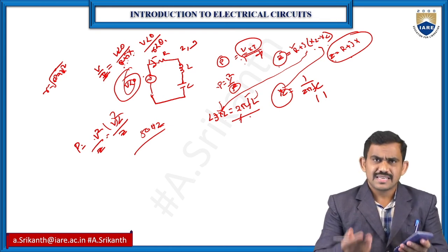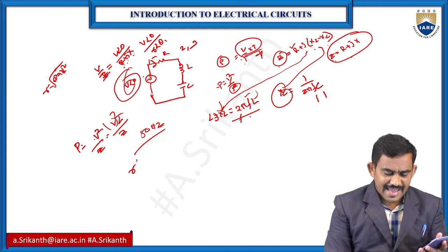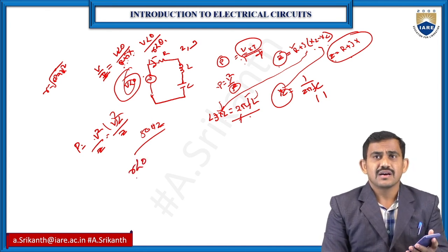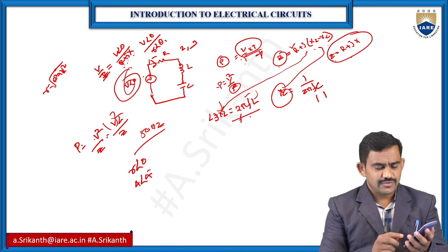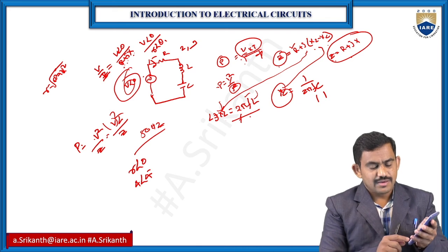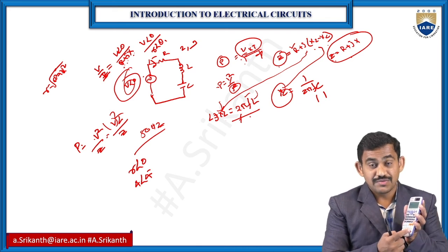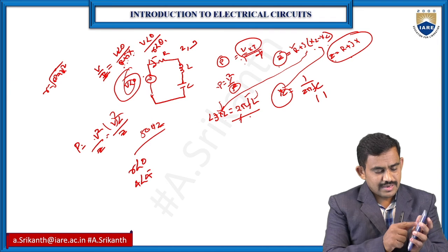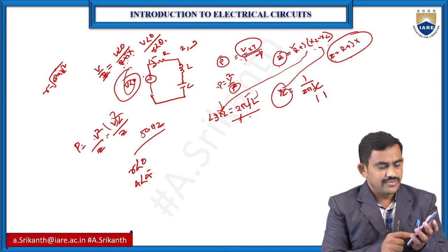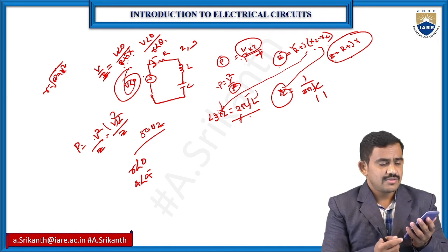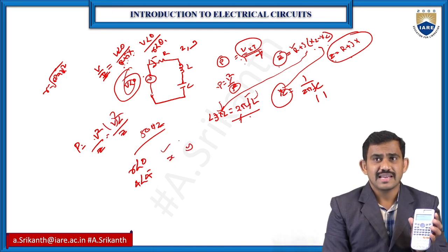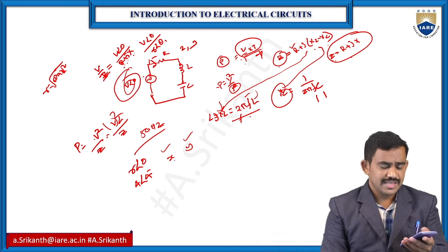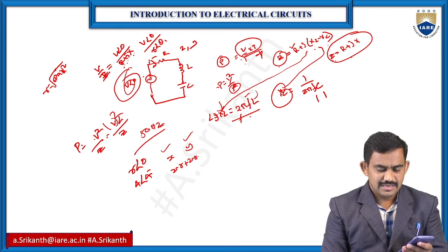Same thing for polar to rectangular. Suppose r is 4 at an angle of 45 degrees. Then shift minus, 4, comma, 45. Then I have the x and y values, that means the real and imaginary values. So the real value here is 2.8, plus j2.8.